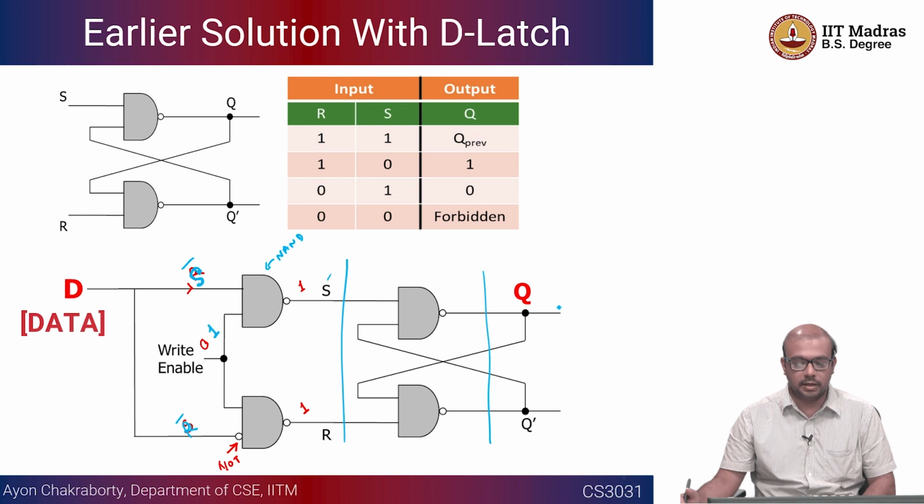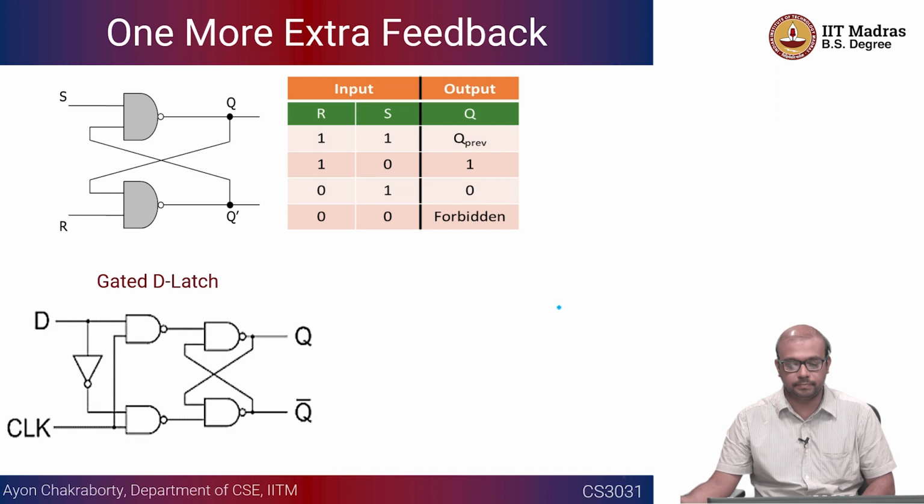and the D latch had one problem. This was level triggered, that's why it is called a latch. And we also saw a solution with two D latches successively joined with each other, with one with a positive clock and the other one with a clock negated, right? So that was going to give rise to an edge triggered solution, which is basically called a D flip flop.